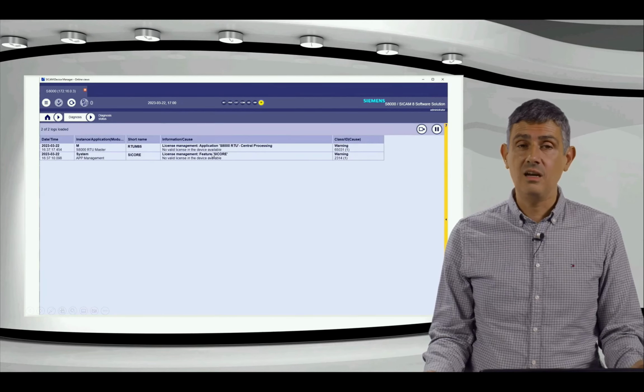Click here and select an event list in the properties. So we are always doing as we are told by the system. We click here, and you will see that now on the properties, we can select the event list. So we select the event list total, and then this picture is ready to display the event list.